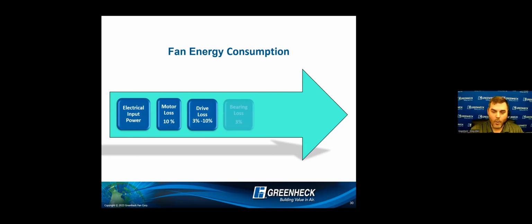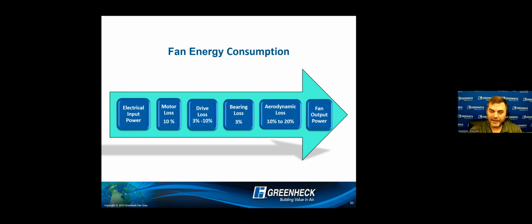So FEI is a wire-to-air look at a fan's efficiency. I mean, literally on the left-hand side, power in, on the right-hand side, fan power out, right? This is a beautiful way to look at efficiency. And what we're going to do is compare the fan you picked at the performance point that you picked to a baseline calculation, a baseline fan. And that relationship, that ratio, is going to give you a single number FEI value.